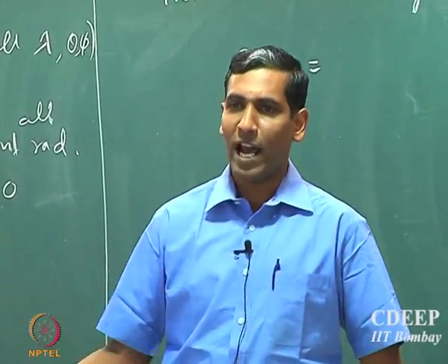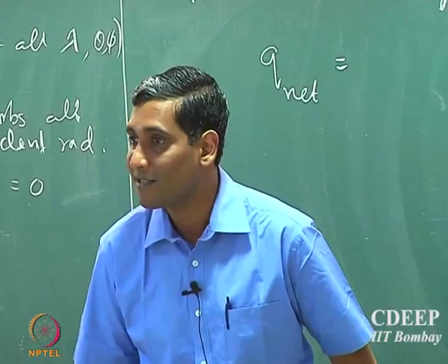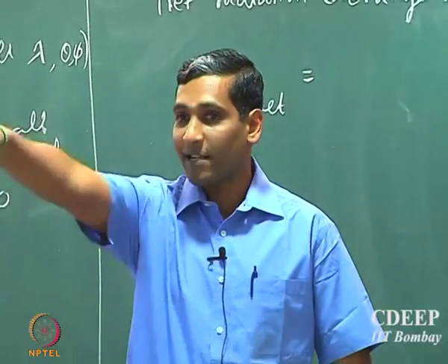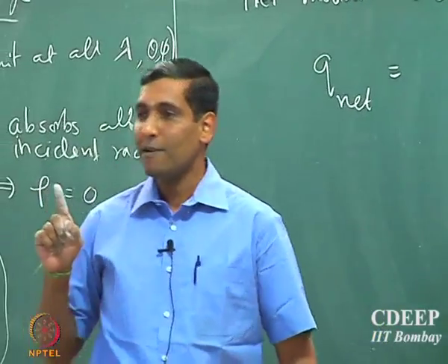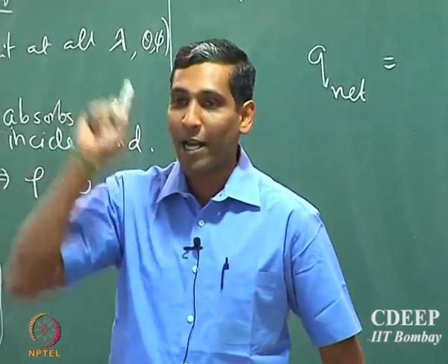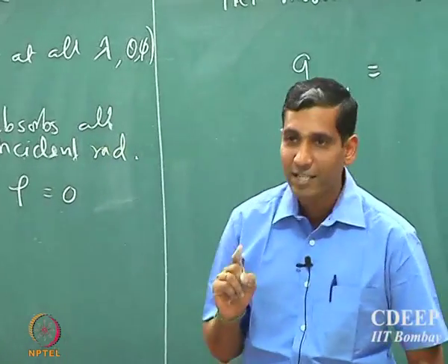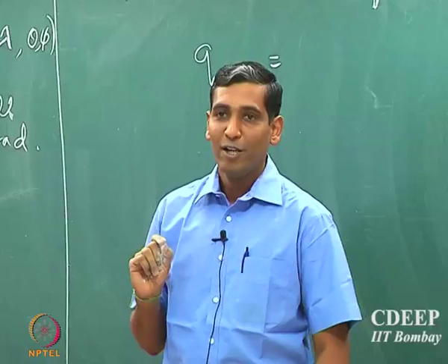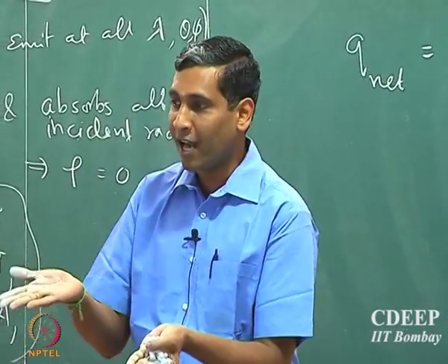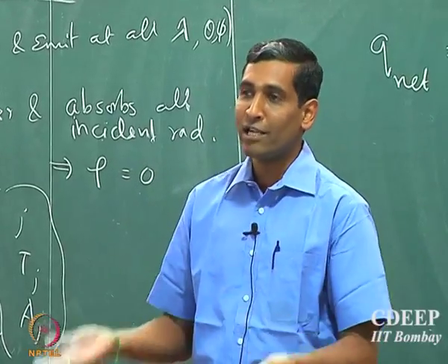That's fine, it's a Blackbody, so it has to be a diffuse emitter. It's a Blackbody, so it's Blackbody radiation. View factor, you see? So that's the first and primary assumption that you make. You assume that view factor is 1. So in most of the radiation calculations that you would have done so far, you assume that the view factor, the geometric factor, they are all geometrically aligned, and that the geometric factor does not contribute anything to the radiation exchange.